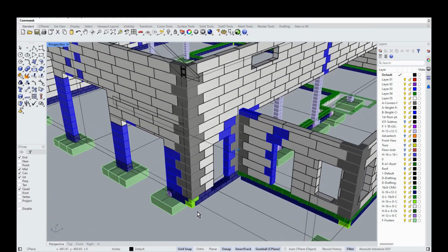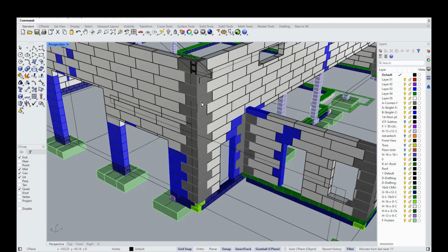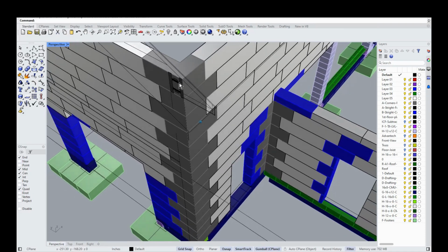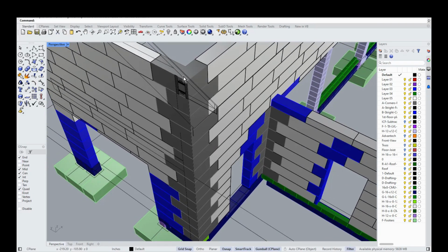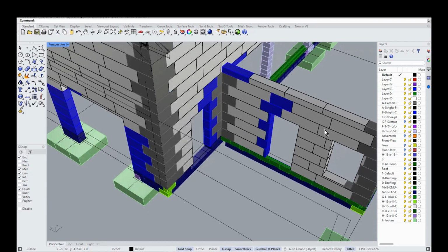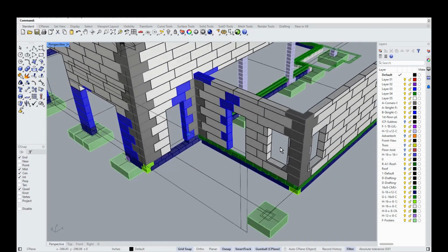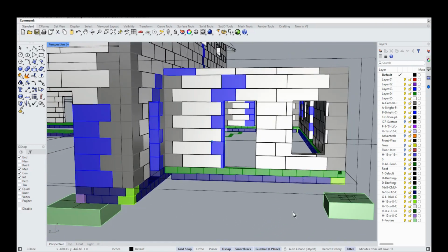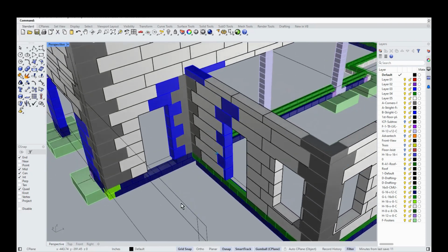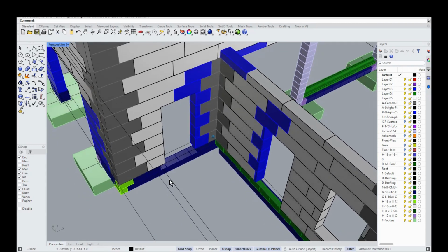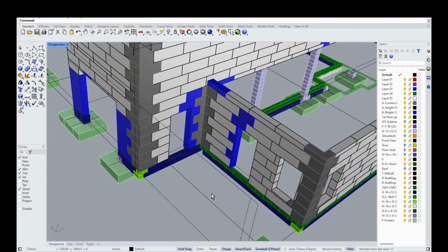But for ICF, you start with the corners. These dark gray ones are the corner blocks. And again, these are modeled to their dimensions too, and Build Block and most of the others are an amplified size of a cinder block. So they're like 4 feet long, 16 inches tall, and then the width is like 11. So the width doesn't really factor into it, but from a planar view, it's height and width. The difference is the styrofoam, the ICF can be easily cut with hand saws or a spiral saw, something of that nature. Whereas the cinder blocks, they're a little nasty to cut. They have a concrete saw, it makes a giant cloud and mess for everybody.